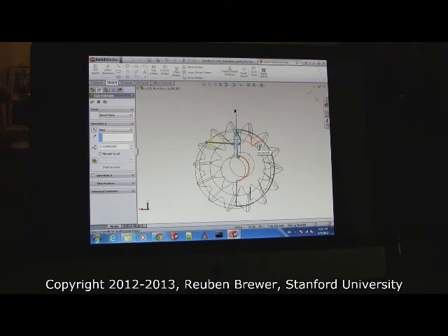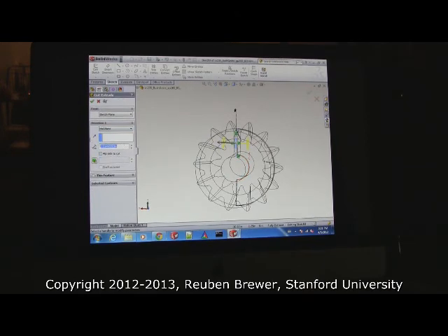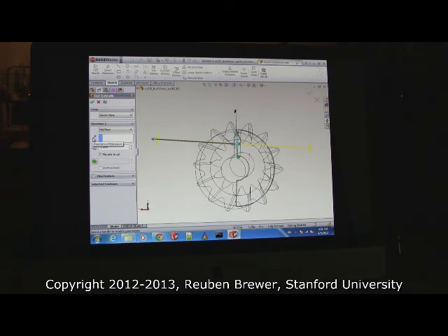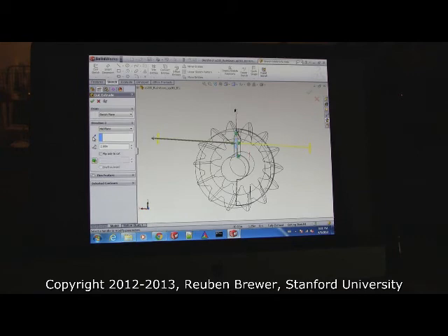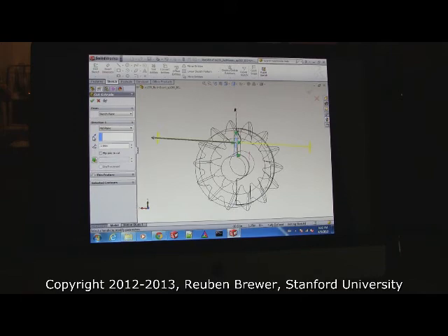3.6 millimeters. Okay. Now exit the sketch through the little purple pencil. And now I want this hole to go all the way through the entire gear. So the way we're going to do that is we're going to go mid-plane and do 2 inches. See how it goes all the way through both sides? Everybody there? So that's mid-plane 2 inches.